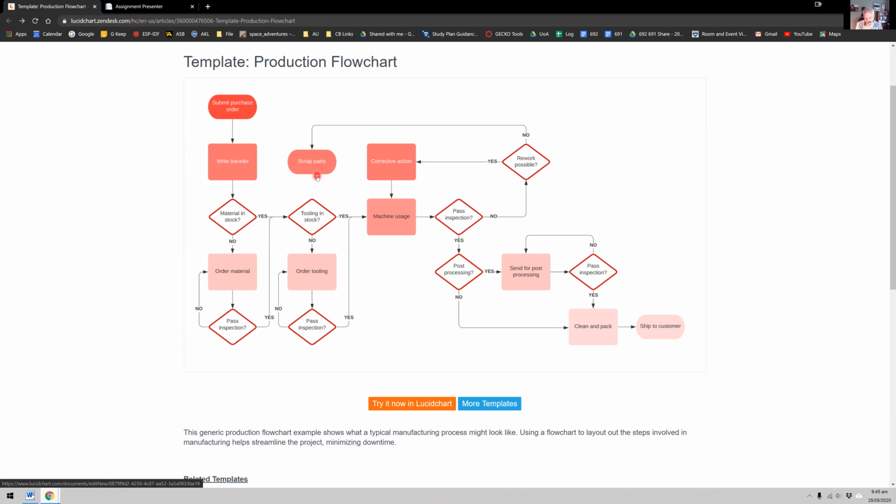So you see, this system is okay up to a point, but it requires a smart person to come along and actually decide, well, this has stopped at this point, I need to do something. Or there is no material coming in, or the material is going to be late, or we can't make that tool, or it's not available anymore, okay? Or what happens if we don't have the right equipment? So it needs a smart person in a system like this. And so if we want a fully robotically computer controlled system, then a flow chart is not very easy to write and manage. So what we're going to do is have a look at state machines.